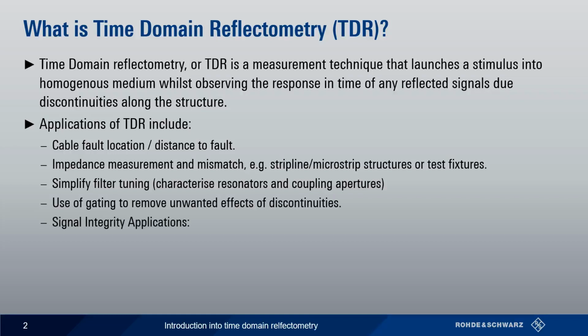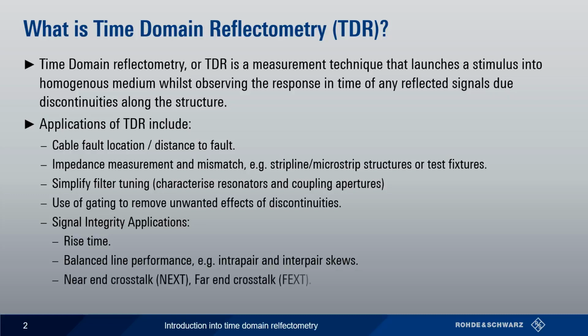And finally, a measurement which is not strictly TDR as it's based on a time domain transmission measurement, but we're seeing more signal integrity based applications now that allow us to measure parameters like rise time, balanced line measurements like intra and inter-pair skews, near-end and far-end crosstalk, and more advanced measurements like eye diagram analysis to characterize the bandwidth of our structures.